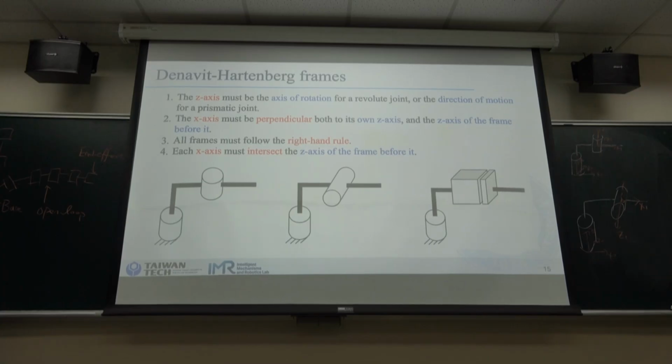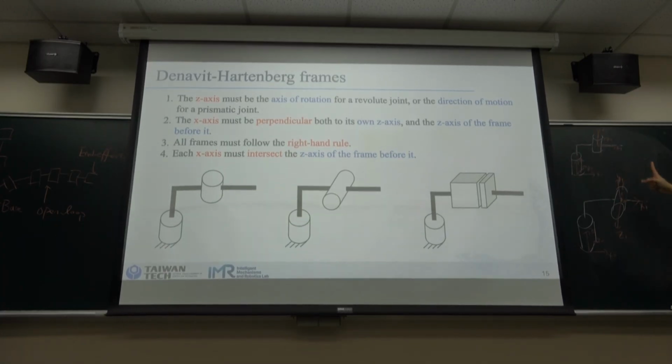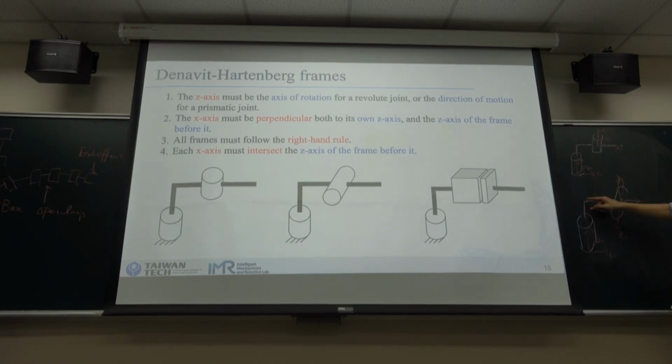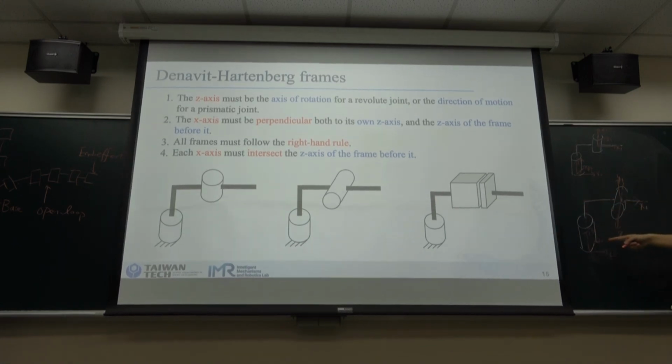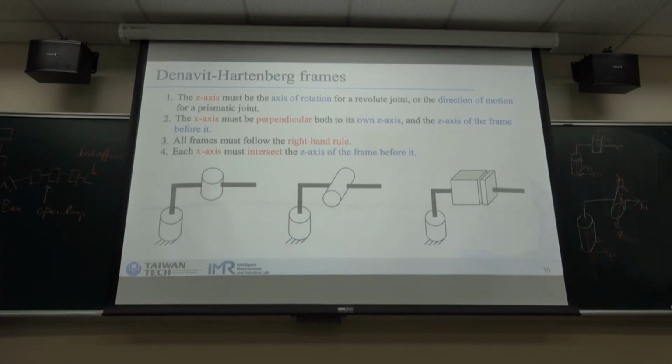And through the right-hand rule, we know that y is pointing upwards. And we check the fourth one: the x-axis intersects the z0 axis. So this frame also satisfies the DH convention.